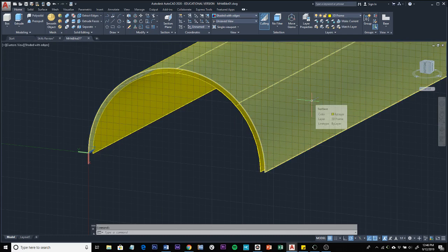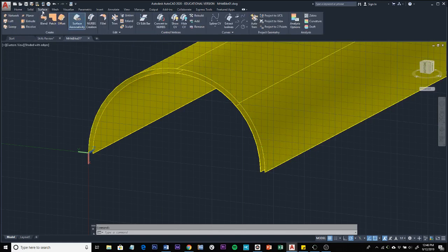So for surfaces, you can isolate any line along this plane using the tool found in the Surface tab. It's called extracting isolines. So we're going to extract an isoline from this surface. So all I did is select this button here, and then it's asking us to select a surface, solid, or face. So I'm going to select this surface, and then you get this red line that you can move back and forth along this plane.